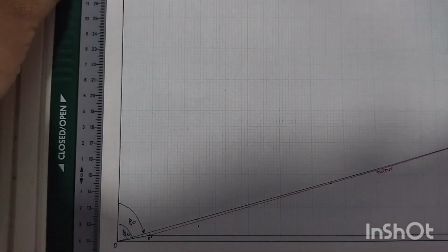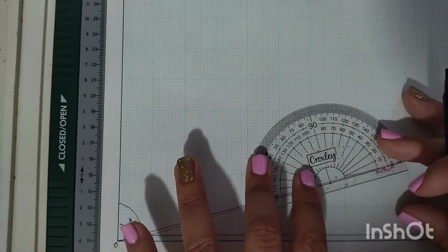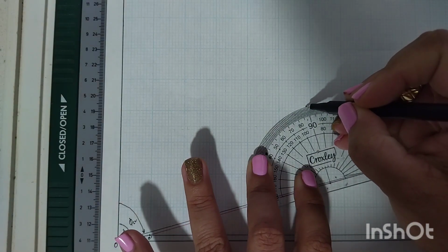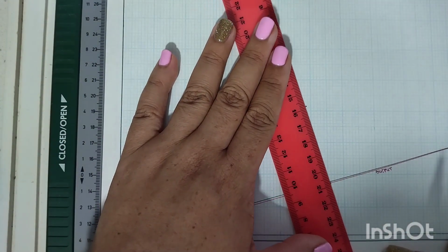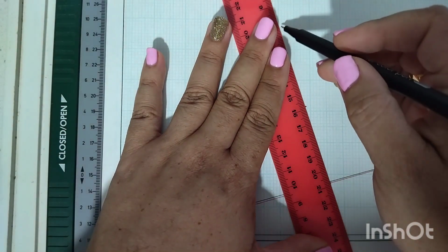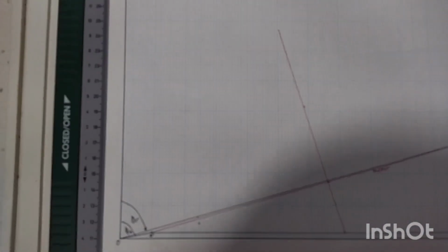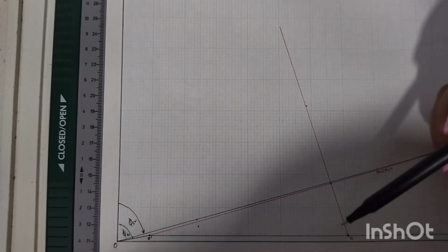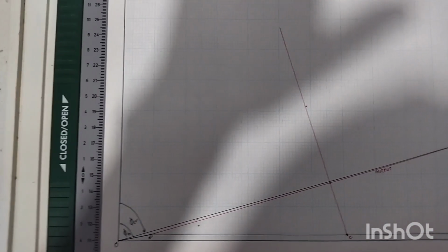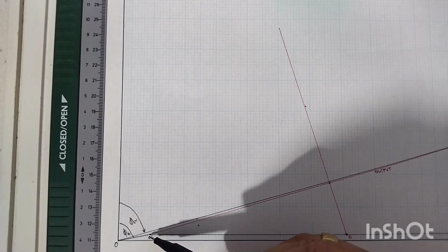Okay, you need to draw. So now you're constructing on your output line a perpendicular bisector. So the line perpendicular to that. There we go. Just a matter of connecting the dots through that point and through that point, however long. At this point, on this line, which is parallel to your horizontal axis, that point over there, you're going to call C. Now, C, sorry, this keeps going out of focus. C, O prime, is the radius of your circle.